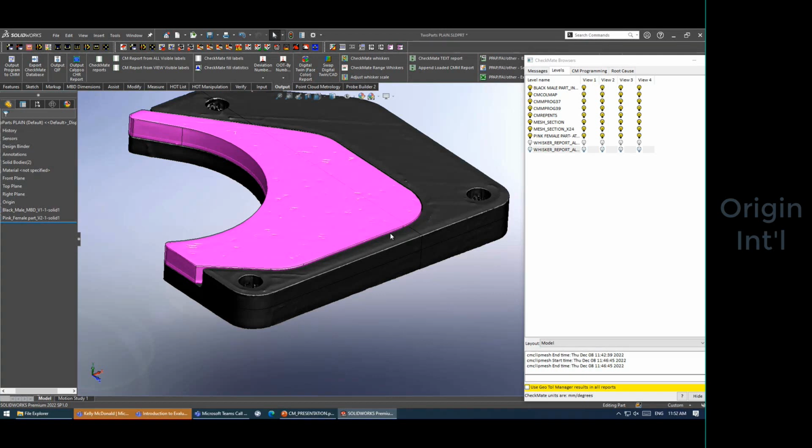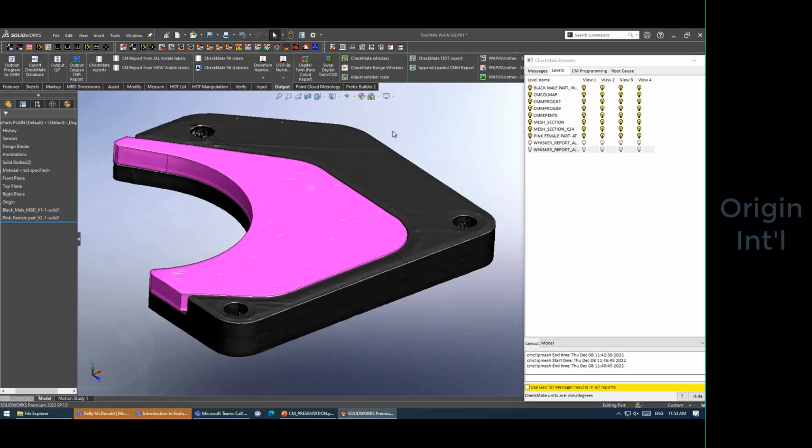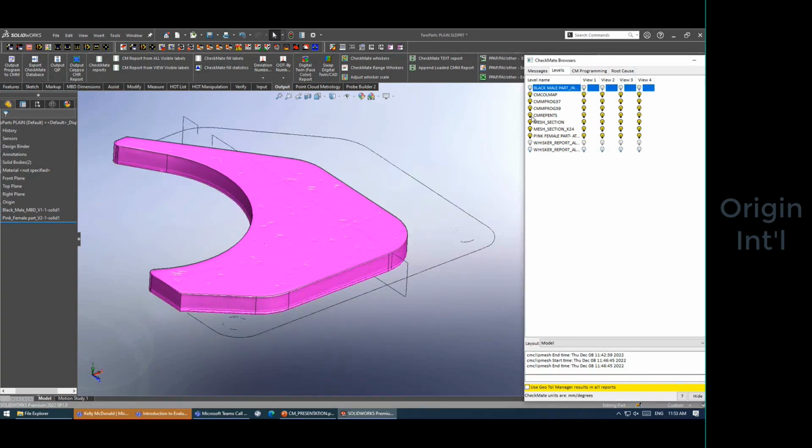Okay, well then it looks like you imported the color map data. Now, what was that from? So the scanner went out and scanned the part and created an STL file. The first time we load it in is just to produce a color map and understand the relationship of where it was scanned in space to where it is on the model. Right. So that data, which was scanned out somewhere in the world, did you best fit that entire data set to the CAD model? 100% yes. Okay, so let me just see how quickly I can go back to that point.